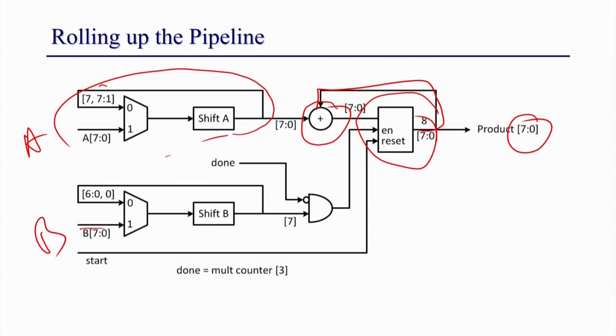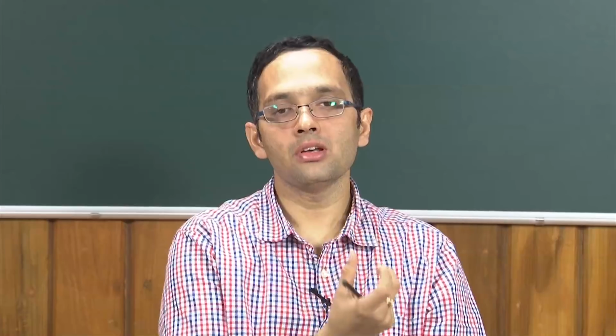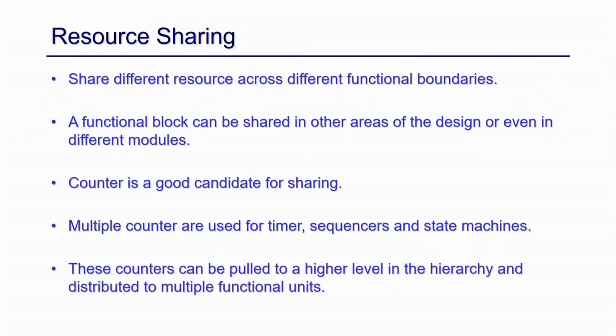So this is about unrolling and pipelining. I am going to talk about the next technique, which is called resource sharing. Resource sharing is again kind of folding, but in a different manner. It is like if you have some resources used in many places, it is not folding into one, but some of the resources I can actually share. It is a little bit different in the sense that the structure may not be exactly the same, but I can reuse that component. It is specifically applicable for counters.